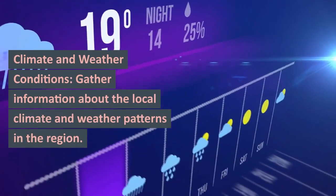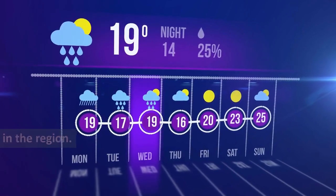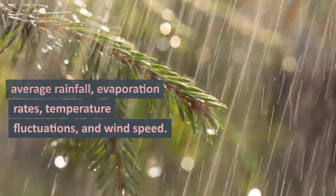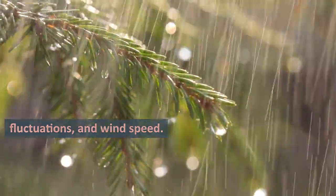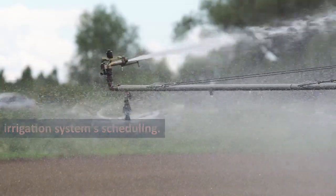Climate and weather conditions. Gather information about the local climate and weather patterns in the region. Consider factors such as average rainfall, evaporation rates, temperature fluctuations, and wind speed. This information will help determine the crop's water requirements and the irrigation system's scheduling.